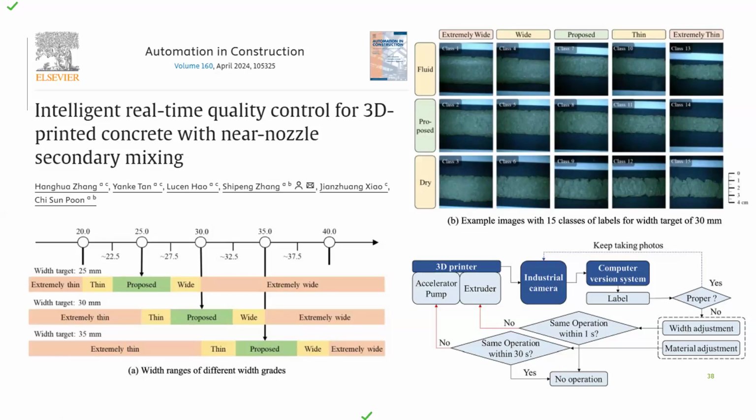So what my friend has done is he prepared a real-time, machine learning based software. He took thousands of pictures of different layers, then trained his model to identify which is the original layer, which layer is now reducing, and where the layer is more thick. Why? Because if the layer is thin, we have to increase the extrusion speed, and if the layer is thick, we have to reduce the extrusion speed.